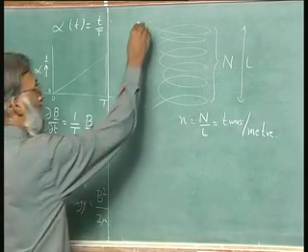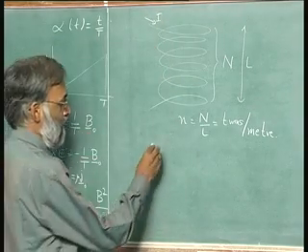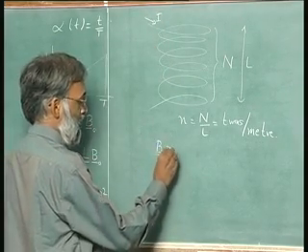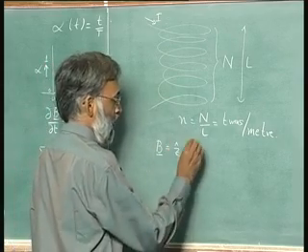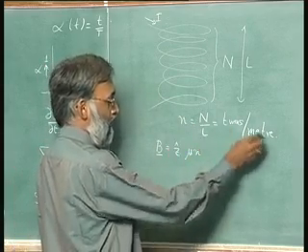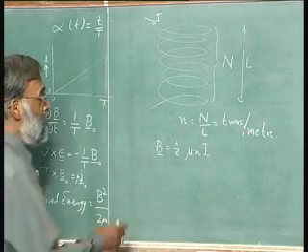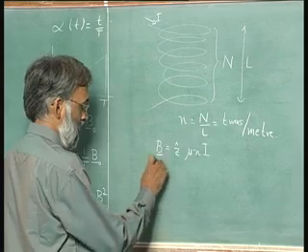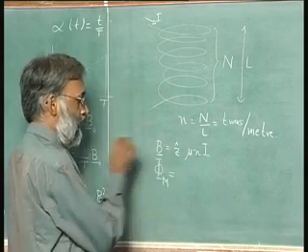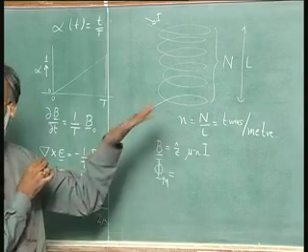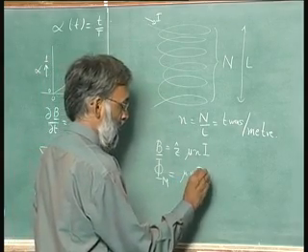Now, if I inject a current, I know that the magnetic field B is in the z direction and is equal to mu times the number of turns per unit length times the current. The flux phi m, phi magnetic, is equal to the surface integral of this B over a cross sectional area. So, it is equal to mu n I times area.